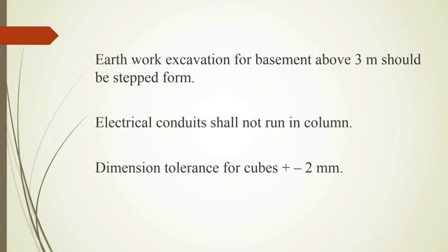Foundation is important for building construction. Therefore, earthwork excavation for basements above 3 meters should be in step form, because above 3 meters there is a risk of sliding. So that is the reason the basement should be in step form. The column transfers the loads, so electrical conduit should not run in the columns. The dimension tolerance of cubes is plus or minus 2 mm, because the cube test is very important for concrete.